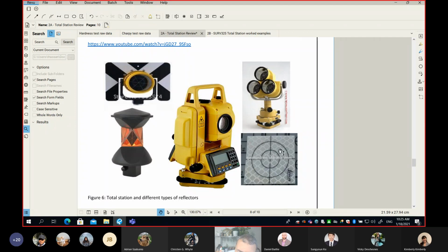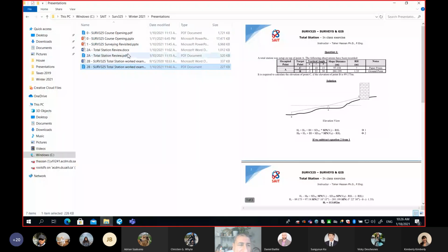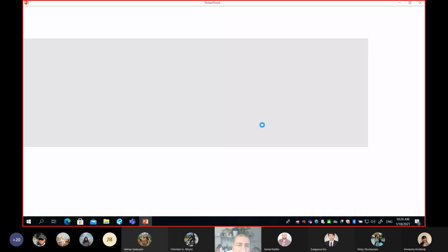And what's good about this one is you can permanently stick it on one point in space. Let's say I can go to a wall and stick this on with, for example, epoxy, or I can probably produce a bracket and attach it to one point in space and leave it there forever. Okay. Now, why is this paper prism or sheet reflector fantastic in some applications? Here is the point. If you remember from the last class, I showed you some application. We call it deformation monitoring.